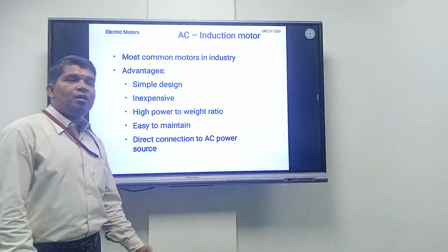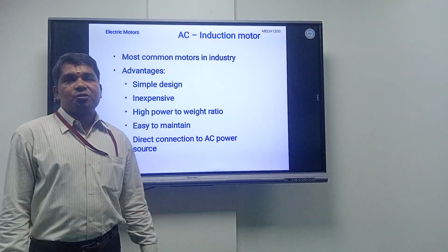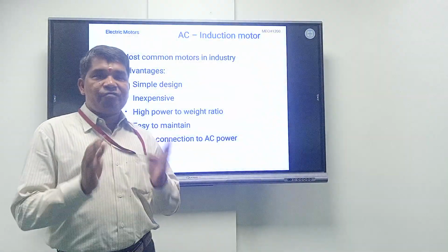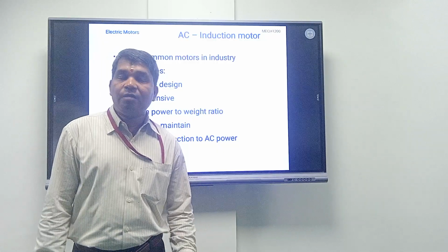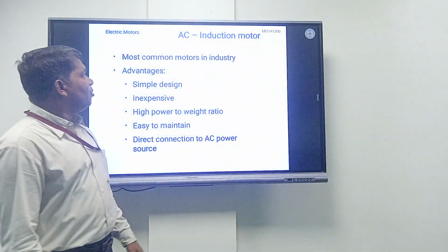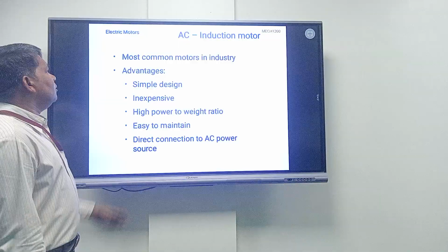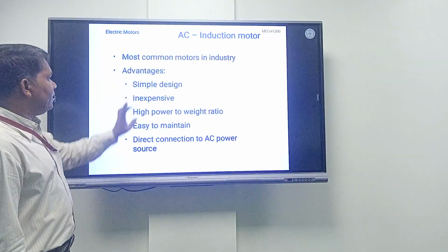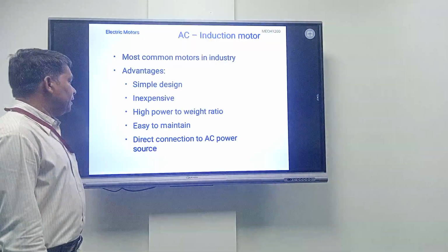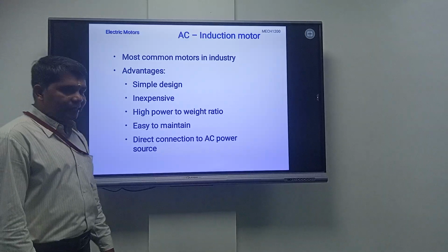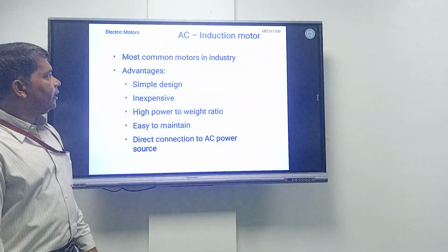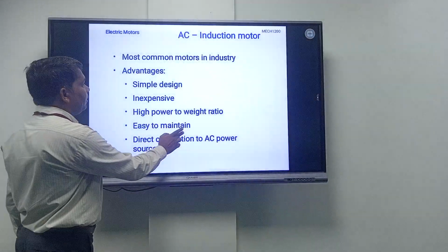Three phase motors are used in high power applications. In small power applications we use the single phase motor, because you cannot make a single phase machine with a larger power capacity. That would make it difficult to construct and run the machine. That's why we have the three phase induction motor. The advantages of the induction motor are simple design, inexpensive, high power to weight ratio, easy to maintain, and direct connection to AC power sources. These are some of the advantages why we use the induction motor in many field applications.